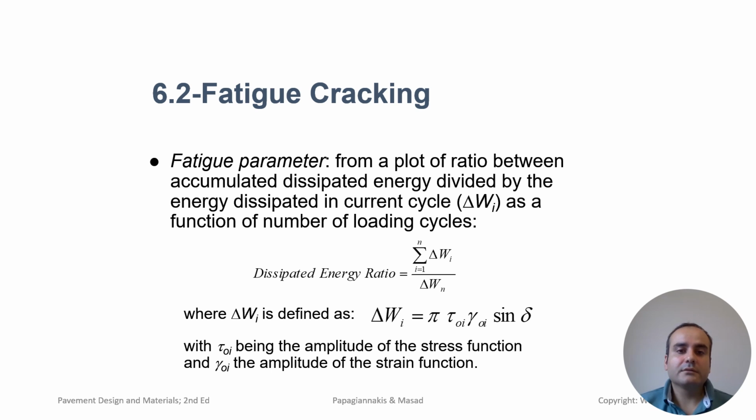Fatigue parameter can be obtained from a plot of the ratio between accumulated dissipated energy divided by the energy dissipated in the current cycle as a function of number of loading cycles, as shown in this slide.